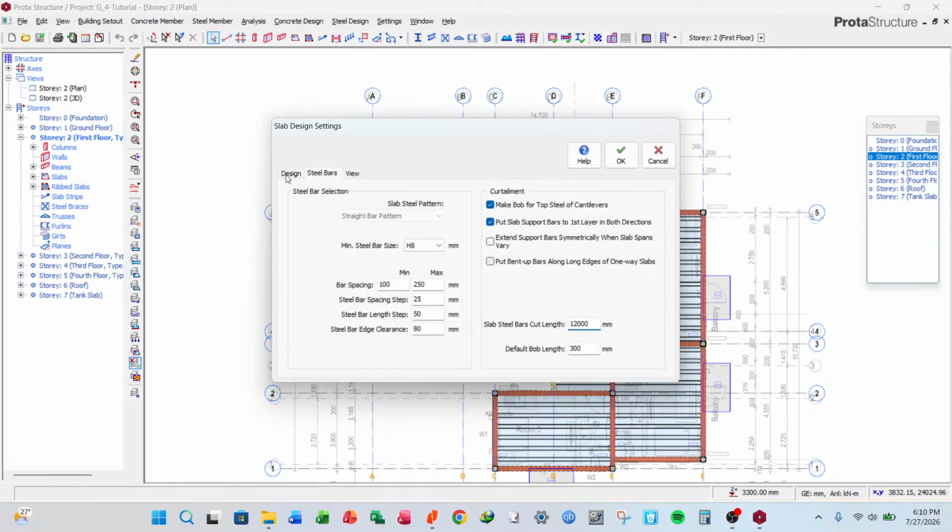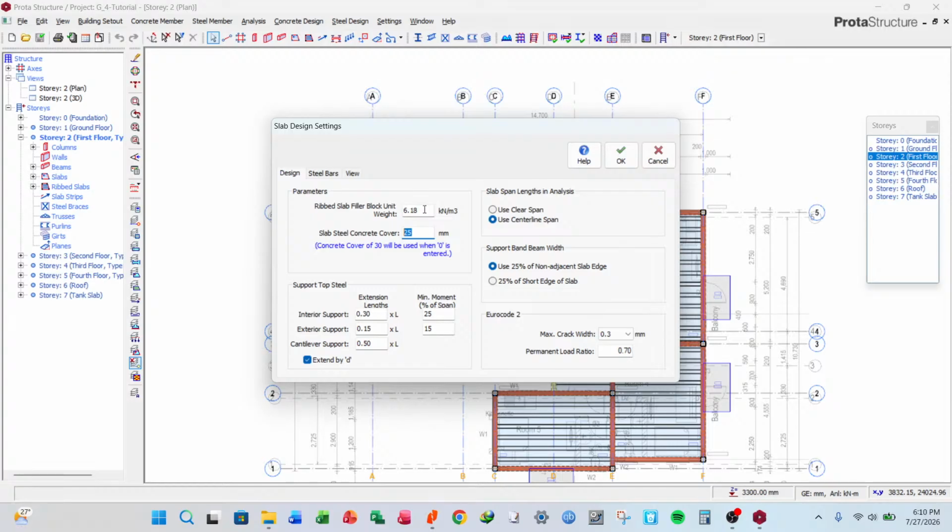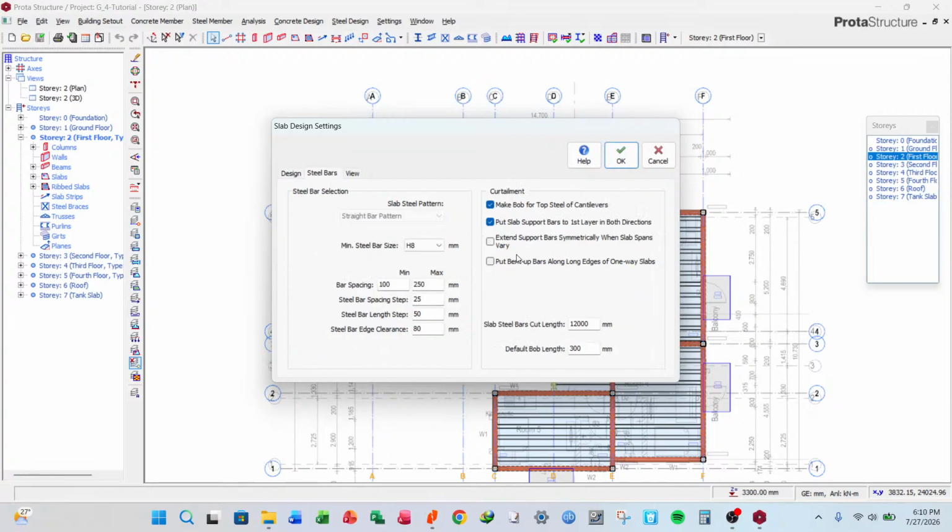Then here we shall adjust cover, which we changed last time, then the bar size. Okay, the bar size. So the minimum bar size for our design shall be maintained at 10 for slabs. Prefer using 200 as the maximum spacing of reinforcements, due to crack width related purposes.